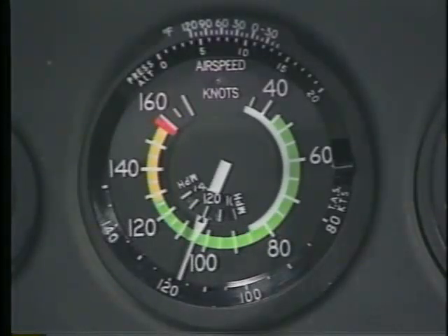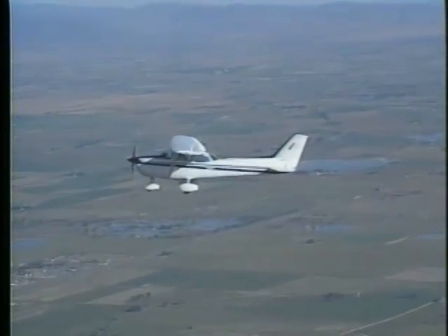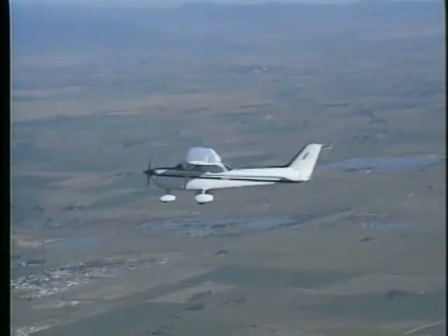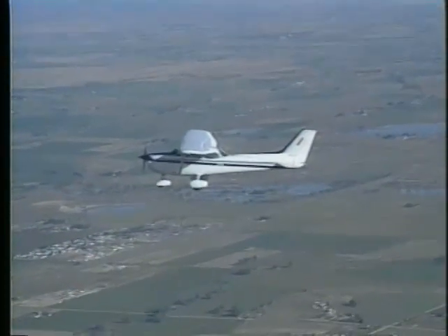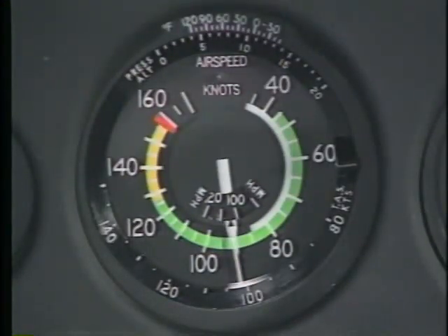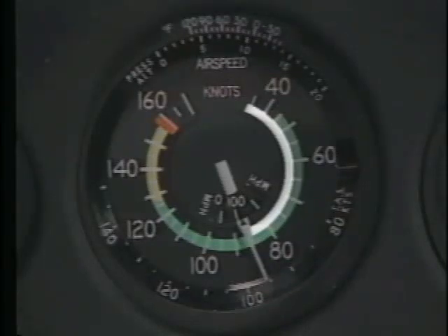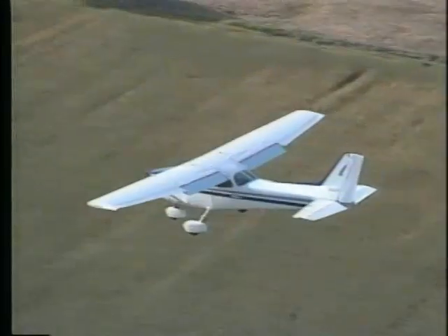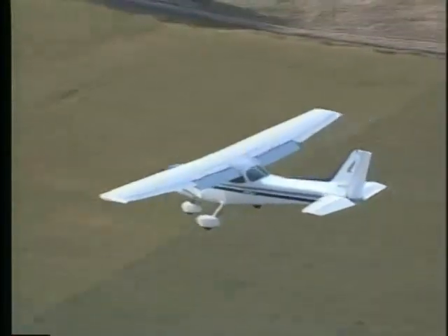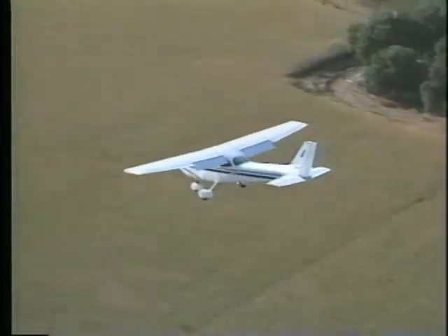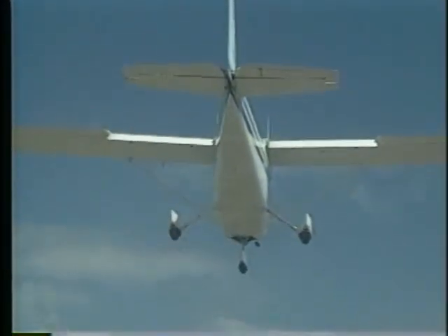The airspeed indicator displays the speed of your airplane through the air by measuring the difference between the ram air pressure entering the pitot tube and the ambient air pressure that enters the static port. As this pressure differential changes, the airspeed needle moves. A number of color-coded arcs are incorporated on the instrument face and represent various airspeed limitations. For example, the white arc shows the flap operating range. The upper end of the white arc indicates the maximum airspeed permissible with flaps fully extended, while the lower end shows the stall speed with full flaps.